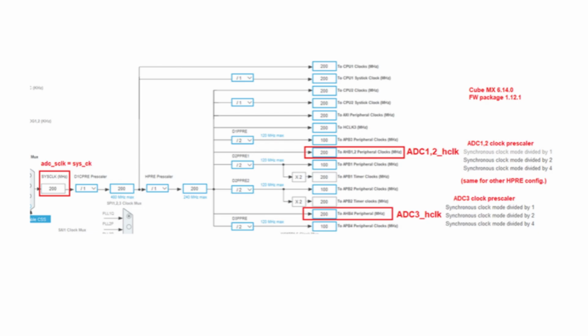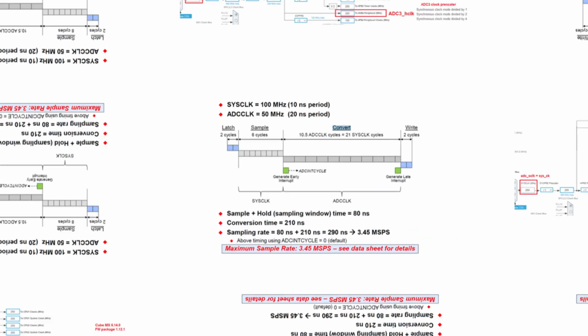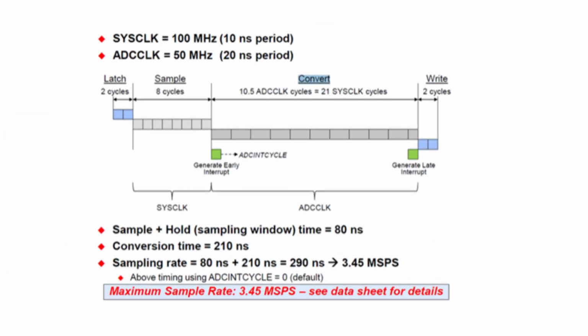Yes, a faster ADC clock generally reduces the overall conversion time, since sampling time and conversion steps are measured in these clock cycles. However, running the ADC clock too fast can sometimes introduce more digital switching noise back into the sensitive analog parts of the chip, potentially degrading accuracy slightly. Conversely, a slower ADC clock, using a larger prescaler value, usually gives cleaner, more stable results, especially when combined with longer sampling times. But again, it slows down the maximum throughput. So it's another balancing act.